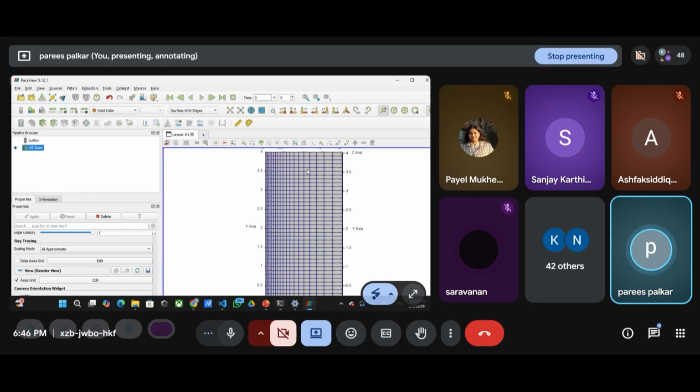I'll refresh now. There will be some refinement in this section as we are in the positive y. See, we have done refinement in the positive x and positive y. So let us say there might be some inlet here injecting fuel from this end. If you wanted to capture this area very accurately, we generally do simpleGrading in this section.